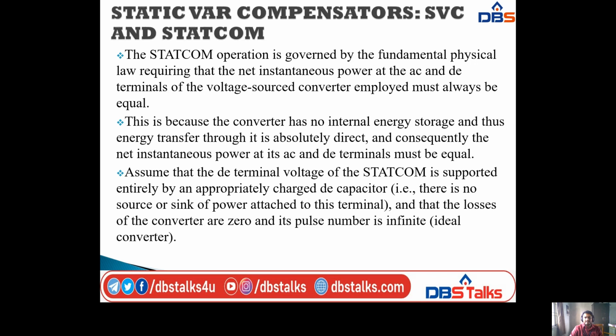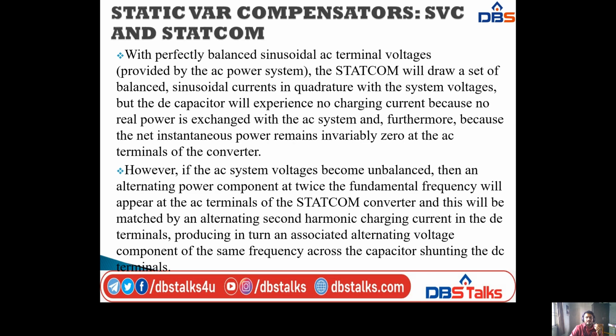Assume that the DC terminal voltage of the STATCOM is supported entirely by an appropriately charged DC capacitor, and that the losses of the converter are zero and its pulse number is infinite. With perfectly balanced sinusoidal AC terminal voltages, the STATCOM will draw a set of balanced sinusoidal currents in quadrature with the system voltages.